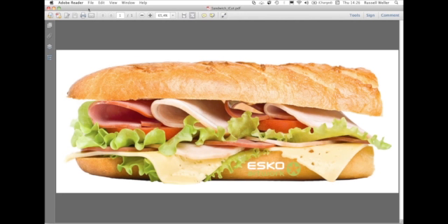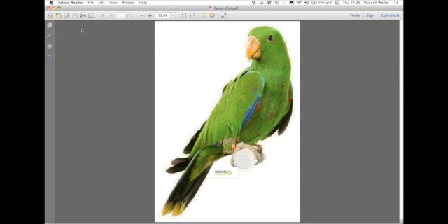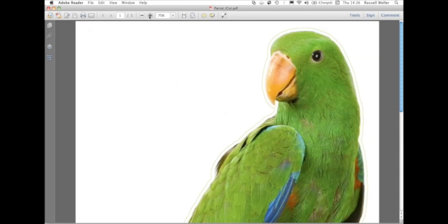One problem you see here, there's no cut path on there, there's no bleed. It's only going to use the trim box of the file for nesting, so all of this white space around the edge is going to be wasted. That's an expensive material that's going to cause me a problem. But I want to nest that also with other types of shapes. And here you can see that this is, again, another shape here. But you'll see this particular time, if I just zoom in, some kind person has created me a cut path.